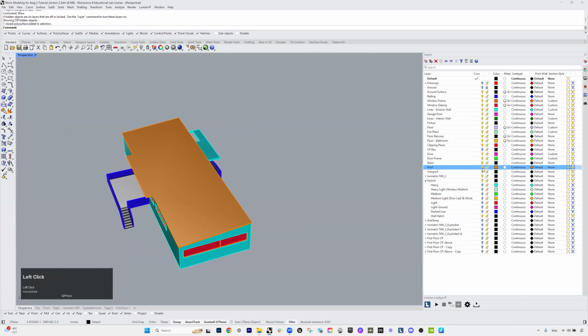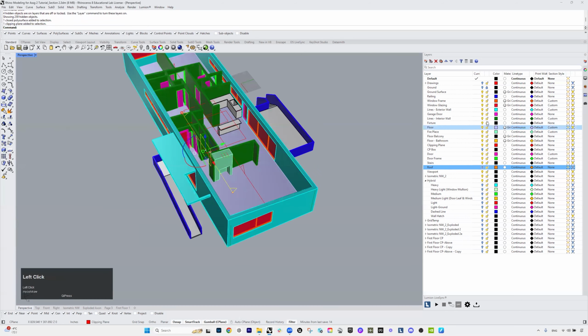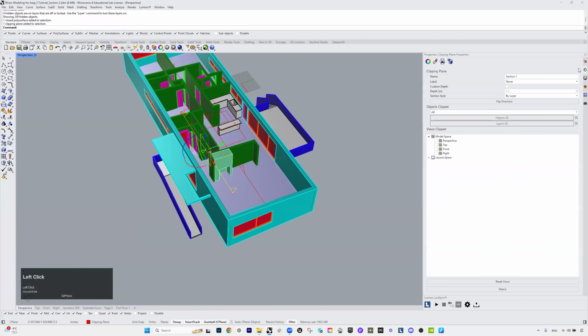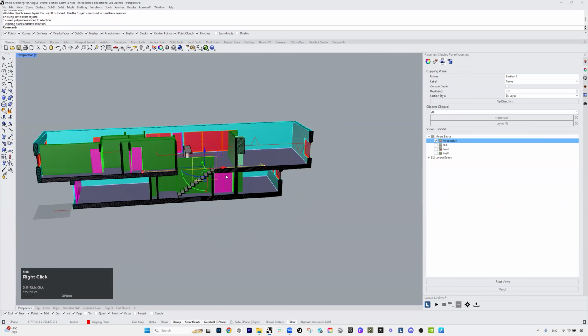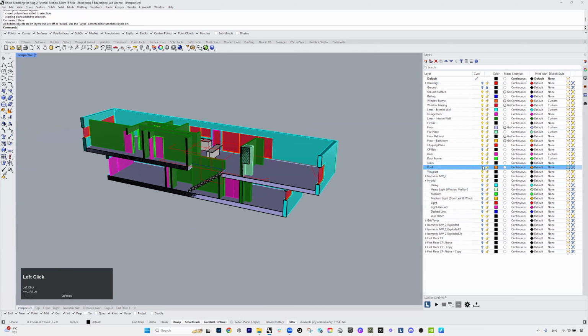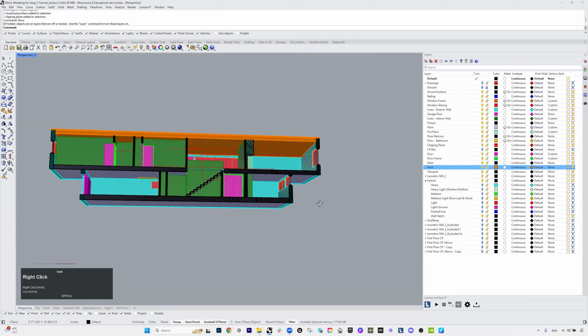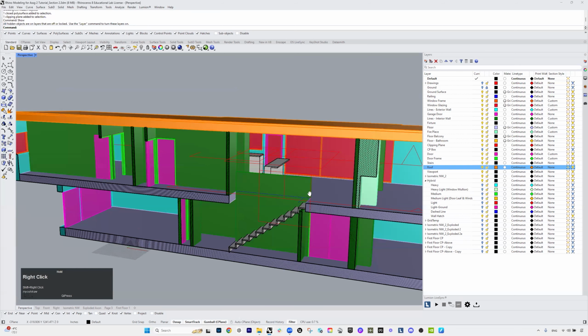I'm going to just hide the roof and then select this clipping plane for the sections. Go to properties, click on this icon over here for the clipping plane properties, and click on this perspective to enable this clipping sections over here, and type show, turn on the roof layers over here to bring back the structures. And this is what I want to see over here.